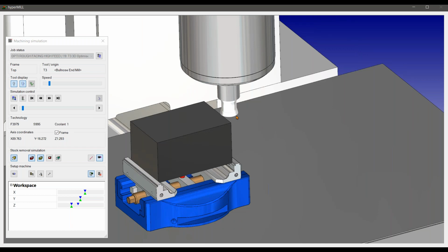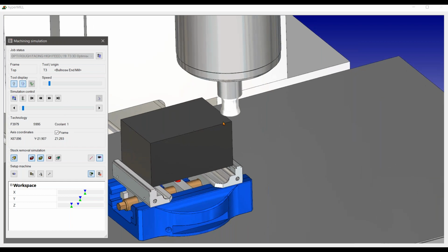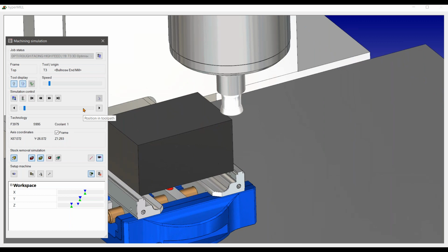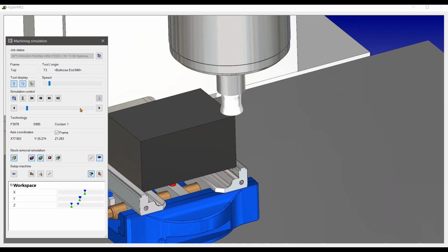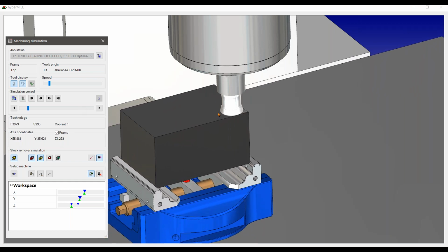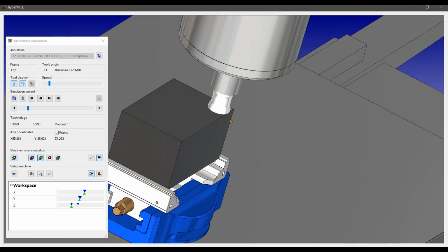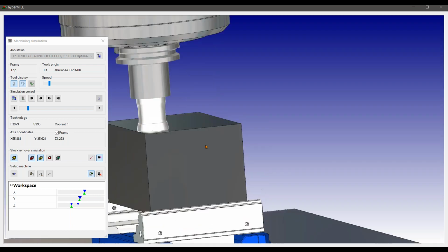It's common knowledge that in hard materials, you should roll into cut, maintaining cutting on one side of the cutter. This is one of the key factors in increasing tool life. This is the only tool path that actually has a roll engagement into cut. This is not an external macro before the cut. This is rolling into cut. It's an arc movement, maintaining cutting on one side of the tool, then slowly increasing into the full engagement.